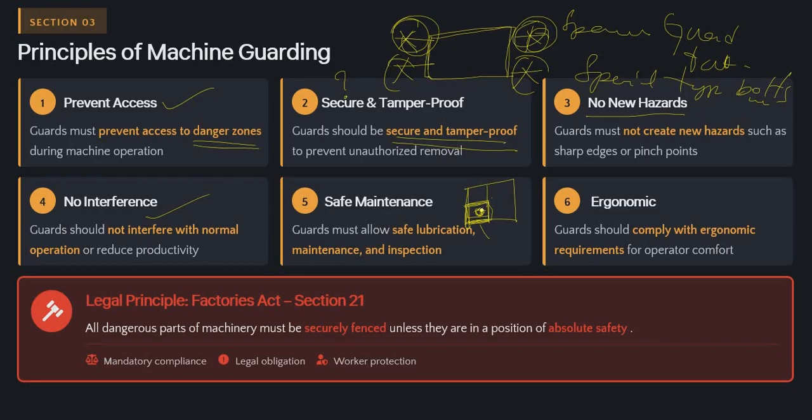So I recommended to them to keep this lubrication point outside instead of inside. There is an inspection door, so you cut one portion and bring the lubrication point up to this level. So from outside itself, he can do the lubrication. Like that, you need to suggest it. So it should be easy maintenance, and it should be easy inspection for the equipment also.